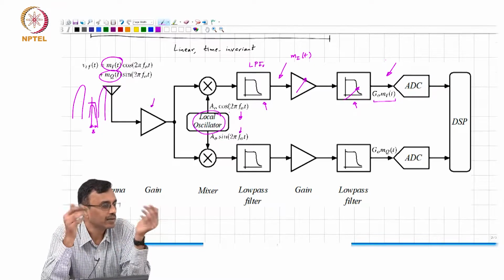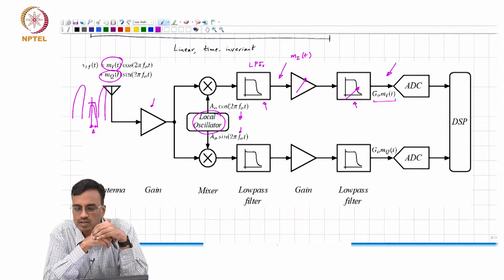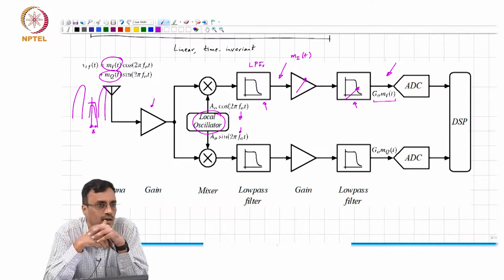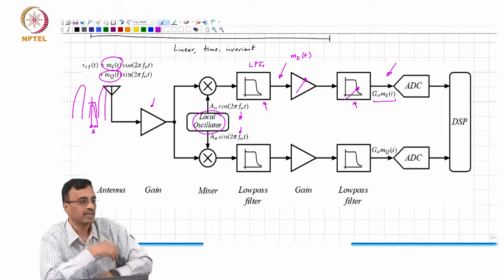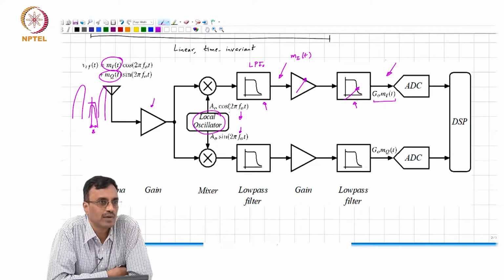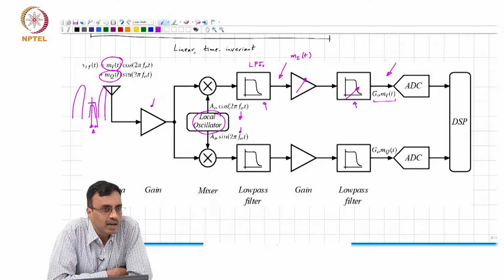So making something very high Q reliably is very difficult. So it's much easier to filter using low pass filters, and as you've already seen in this course, these can be realized very efficiently without the use of inductors, by using op amps, R and C.